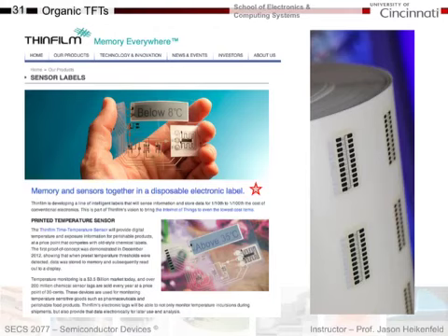One of the really hot developments going on these days, and this is the company I've been following, which I think is really exciting, is called Thin Film. They are now using inks which have organic semiconductors in them, which they can print on a conventional roll-to-roll press on things like plastic and paper, and they're printing both memory and logic. The big breakthrough they had is they've been able to basically get complementary logic, both kind of like NMOS and PMOS, which when you have both, then you can create inverters, and NOR, XOR, etc., and memory, and start to make logic circuits that I can print by the mile and make so low cost on a roll-to-roll process that I can cut these out and put them in all sorts of products like smart cards.